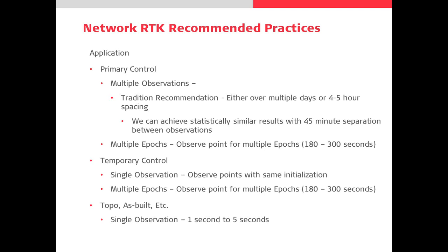I'm going to observe the points with the same initialization, however. So I'm going to observe point 1. I'm going to walk down range. I'm going to observe point 2, with the same constellation, with the same initialization. And I'm going to observe multiple epochs. So I'm going to observe with 180 to 300 epochs.